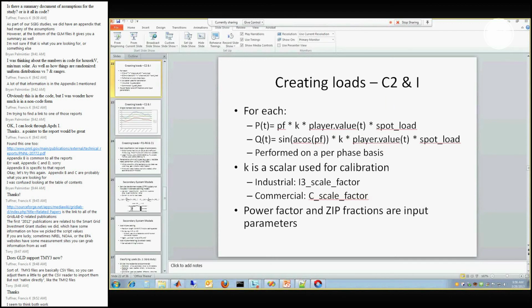Something to point out really quick on the whole sequence conversion thing. As Jason mentioned, you can set it with the nominal voltage and it'll automatically populate the plus minus 120. The caveat is it only does it for the very first one. So if you were trying to do what we were doing in these studies with a player driving that, after that first step, the nominal voltage won't be adjusted automatically anymore. You have to play it into the individual A, B, and C phase. It's only on the initialization that it'll take that nominal voltage value and automatically populate the 0, 120, and minus 120. So if you want to get the subtransmission effects, you do still have to put those in directly as the voltage A, voltage B, voltage C.